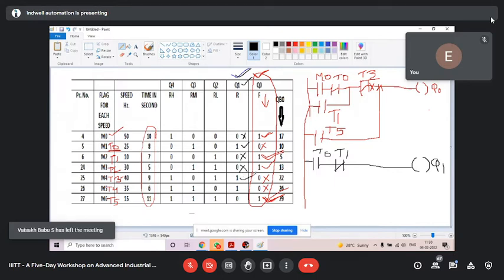Now it is on. What is the signal? T3 NO. Correct. Very good. So you have to take after this because it has been breaking this path. If you will take here, it won't go to Q0. So it should be from outside. Consecutive, you leave. And finally, it is off. So for off, what is the signal? T5. Break this. Your Q1 is done.